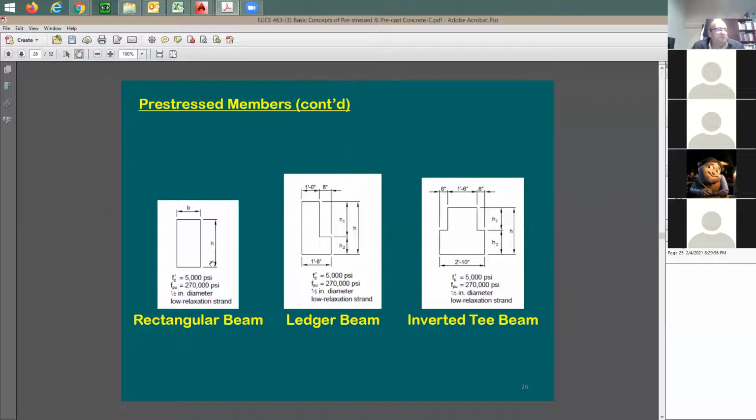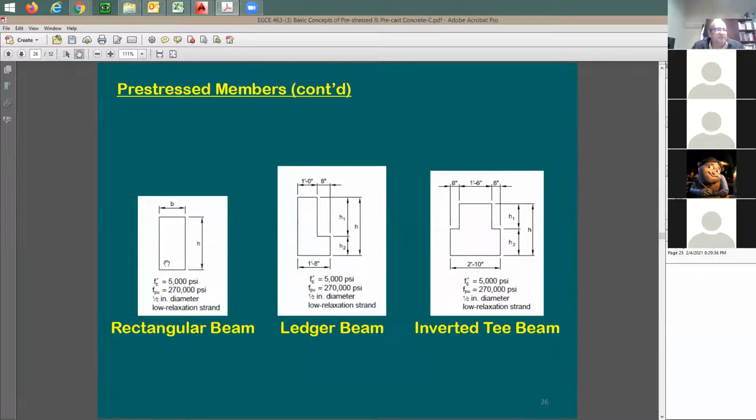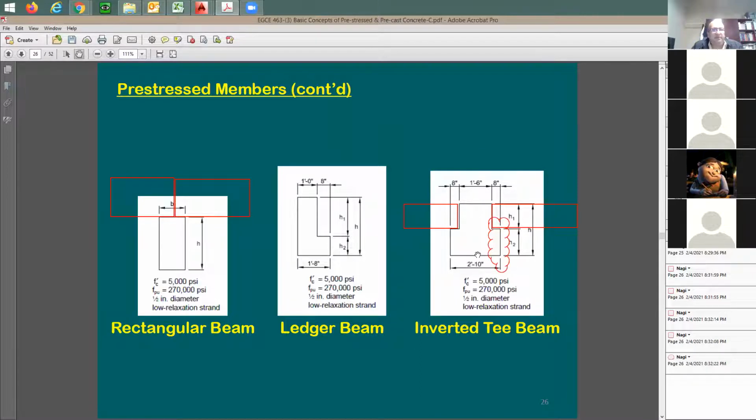When it comes to beams, sometimes we have these rectangular beams. And in this case, if you have a double T or another thing, it's going to come and sit on it like this. And the other double T is going to come from the other side and sit like this. So it's going to be totally supported. In some other cases, the double T is going to come and sit like this, and from the other side, it's going to come like this. So this is going to be like an inverted T, and then it's going to have a ledge. So which part do we call the ledge? The ledge is going to be this part here. This piece that sticks out, right? So this beam is going to have two ledges. You just bring the double T and you put it right here.